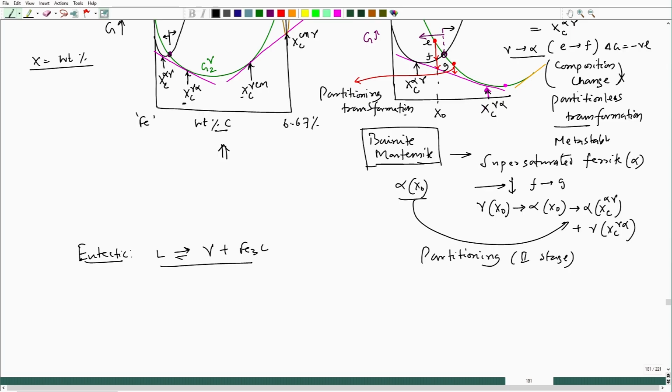And in both the cases we have considered Fe3C. And actually Fe3C, if you hold it for a longer duration, can convert to iron plus carbon, and this carbon is in the form of graphite. Okay. In cast iron, we do see such a situation where we have alpha plus graphite, and this can have different morphology. We can have different cast irons. Okay. So, these cast irons could be grey cast iron, spheroidal graphite cast iron, or malleable cast iron.